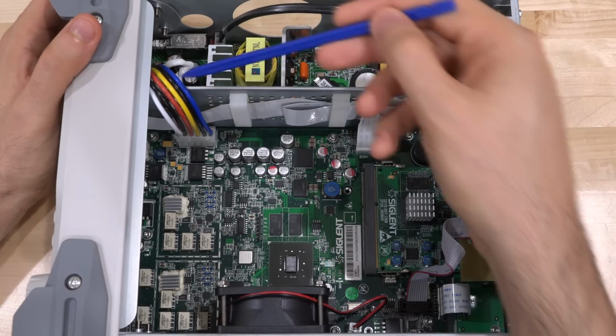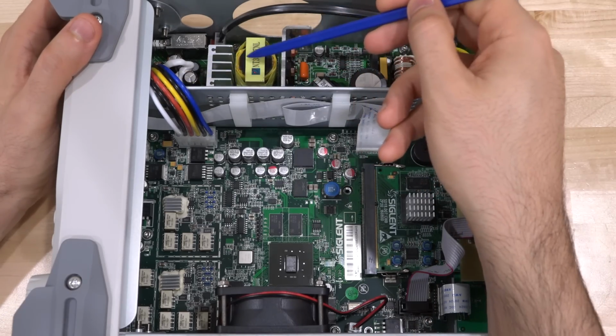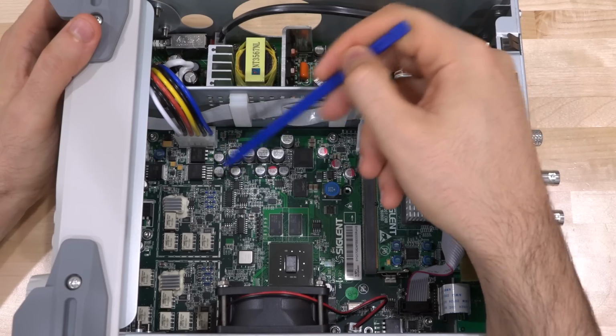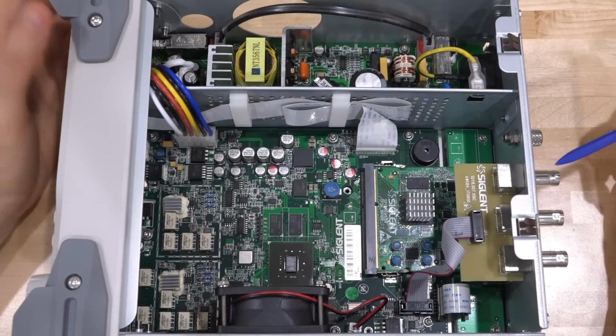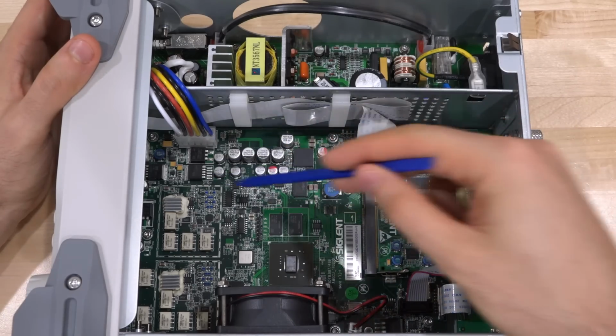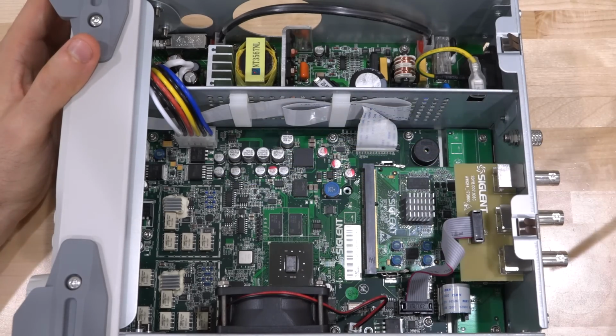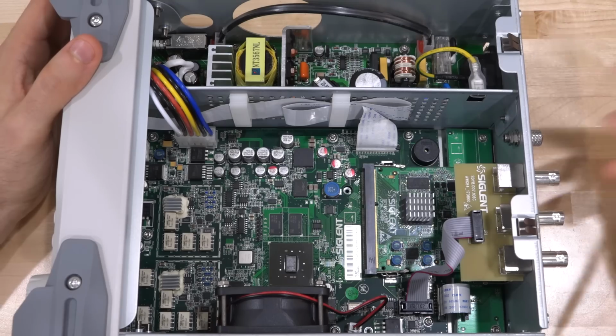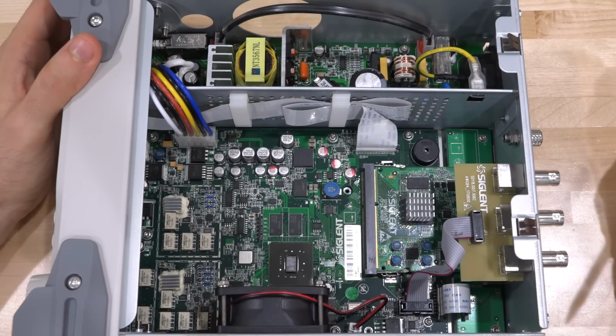Now, if you look over here, the main DC-DC power conversion stage of the power supply has its outputs directly connected to the main motherboard, and of course on that motherboard we're going to find not just all the power conditioning circuitry, which you can see all over here, but there's a lot of other interesting things. The main outputs and the data converters and everything are on that board. We will take a close look at that.